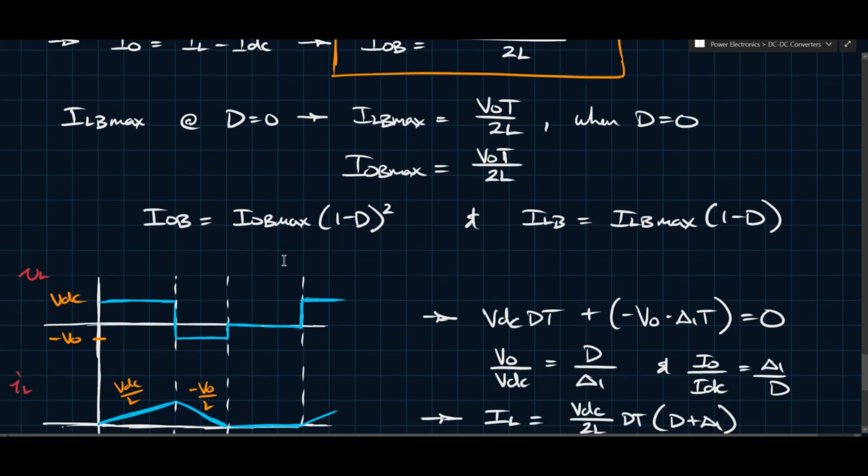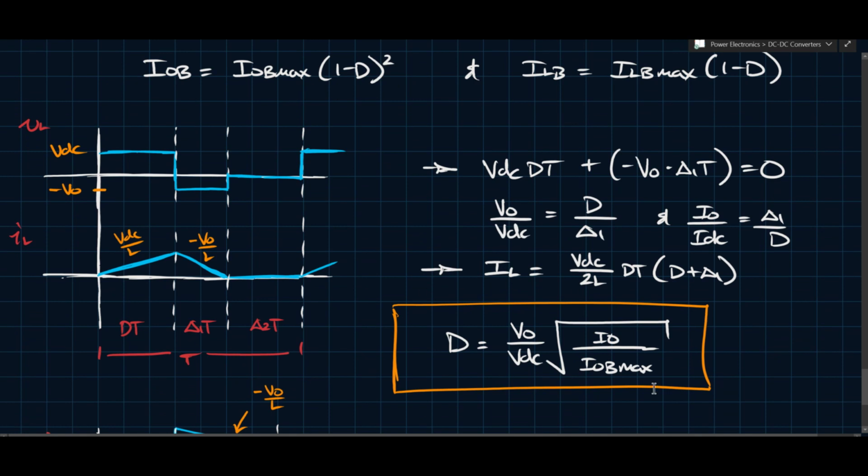We only ended up using one of them really for this duty ratio in DCM. And so in DCM, we saw that obviously the inductor current will be 0 for some substantial portion of the interval, and that's what we call here delta 2. Based on this mode of operation, we established using the VSB, or the volt-second balance, that this is what the conversion ratio should be.